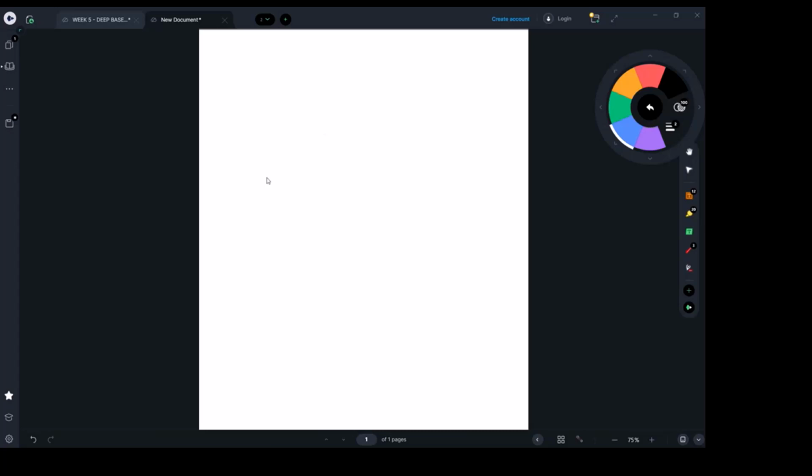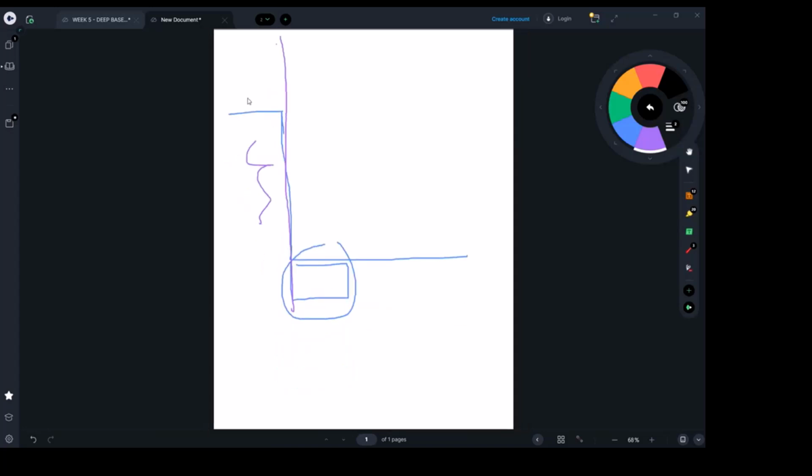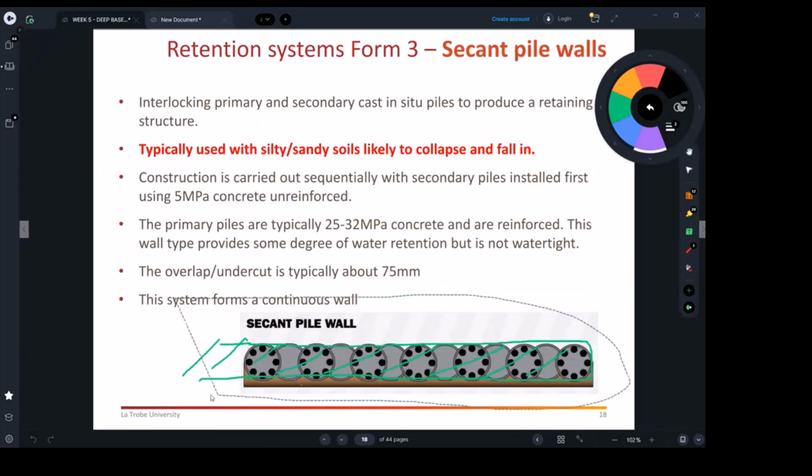But physically, you can't. How are you going to excavate? You cannot just cut the ground at 90 degrees and expect it to stand like this and wait for your panels to come and sit. It's going to collapse, right? And also you're going to need some footing here. You have to think about it carefully, because if you've got a boundary line, the purple color here is a boundary line. You're not allowed to touch the soil, and you have to keep it safe for the neighbors as well. So that's kind of the reason.